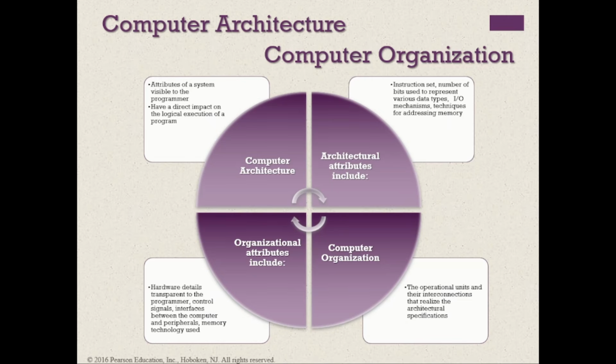The organizational decision may be based on the anticipated frequency of use of the multiply instruction, the relative speed of the two approaches, and the cost and physical size of a special multiply unit. By this example, it is pointed out that architecture is more on the side of the software details, while computer organization is more on the hardware details.